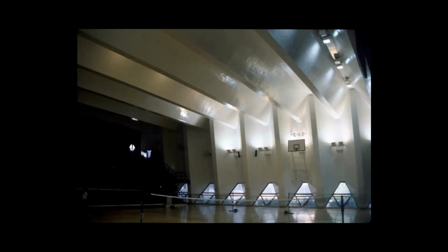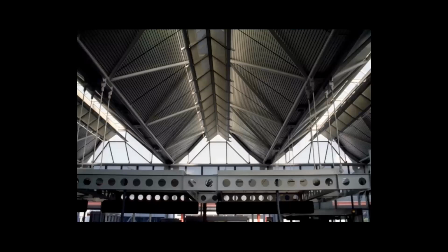This would be a very heavy building because of the weight of all that concrete roof. And so this is a good solution for a country like Singapore, or Hong Kong, which doesn't suffer from earthquakes. If you are in an earthquake zone, this is a far better solution using folded plates, where the plates are like inclined trusses.